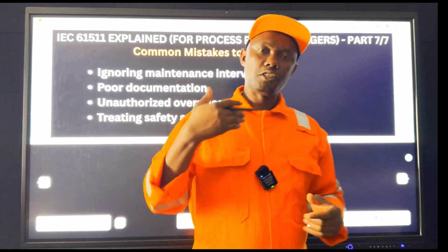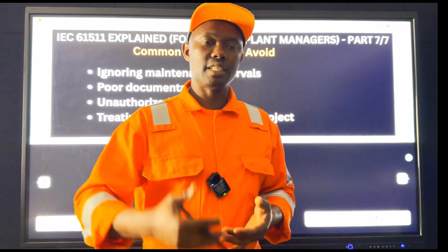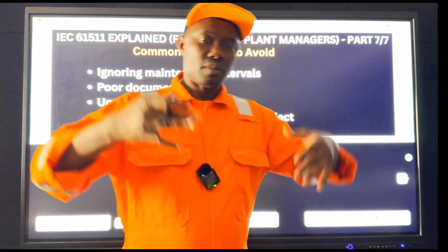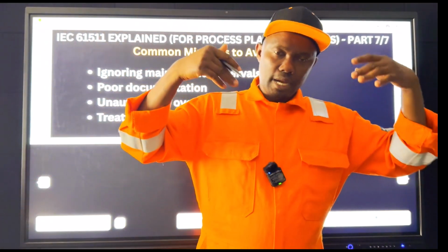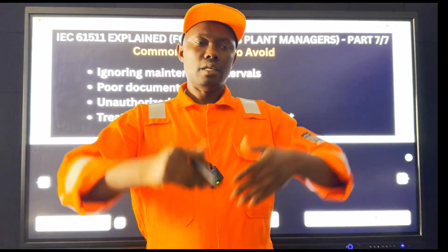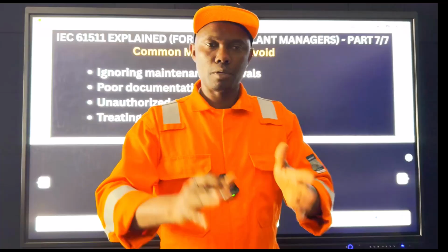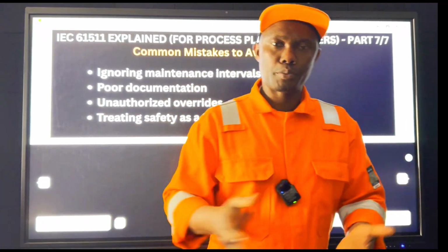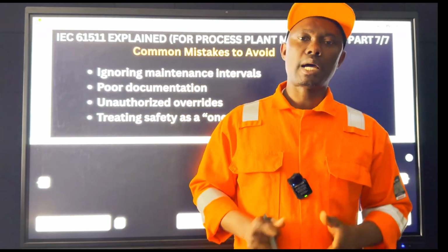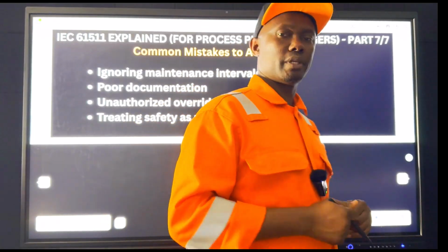No. You still need to track your maintenance and your proof testing intervals. You need to make sure that all modifications go through the MOC process, go through impact analysis, have a modification work pack developed and go through the review process, approvals and all that before you carry out any modification in the safety instrumented system.